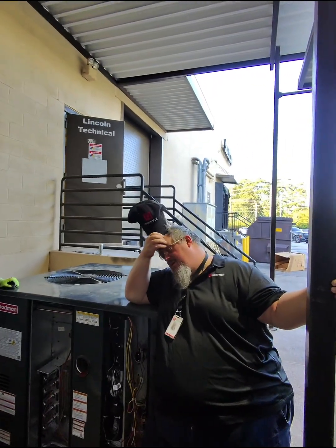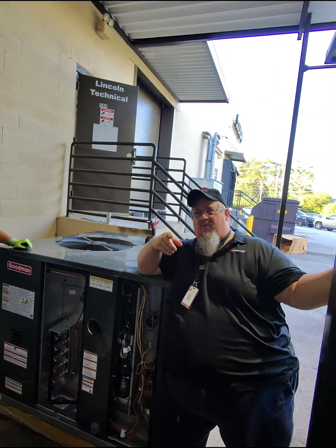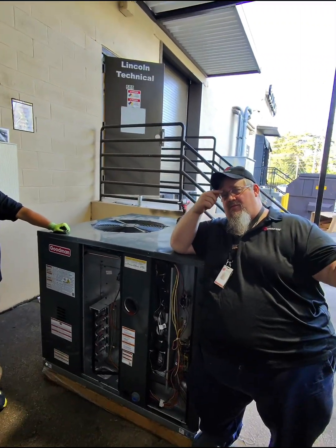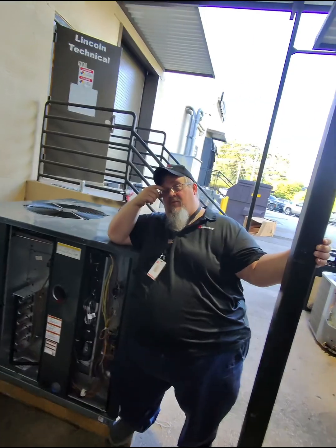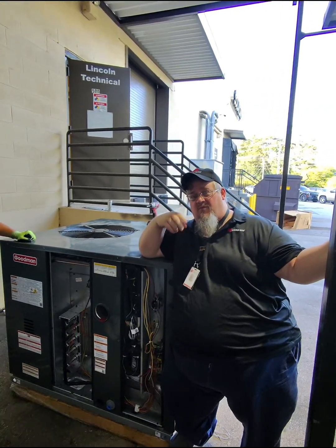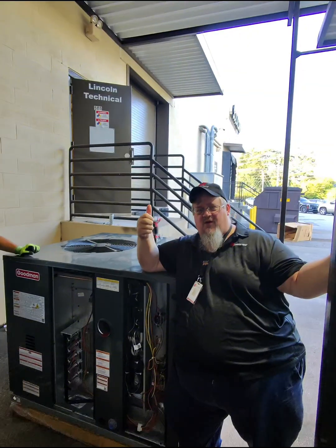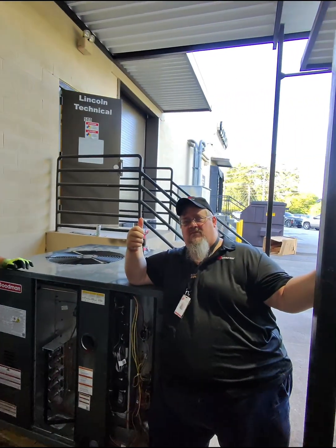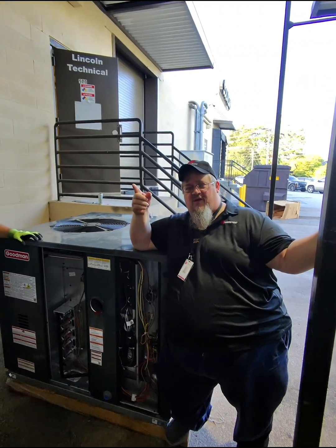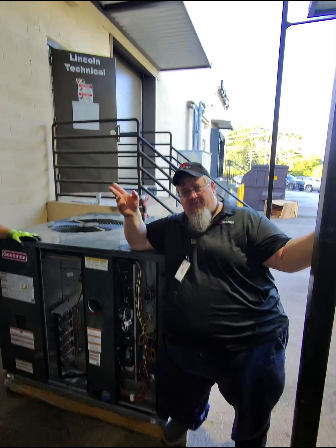Yep. And then what happens? Blower comes on after the delay. Now we got heat, and it's blowing. It has a time delay, then your blower comes on. And we're good to go, until what? Until we reach temperature, until we're satisfied, and it shuts down. Hopefully we don't have any safeties, right?